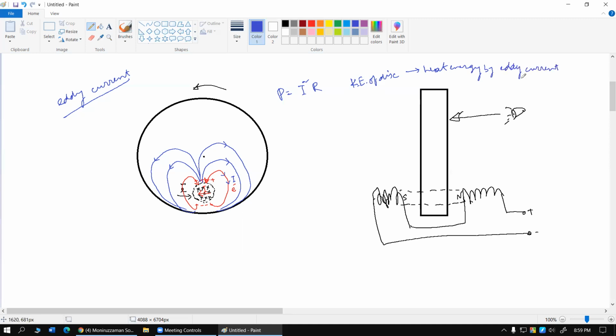which means as long as we keep the magnetic field turned on and the eddy current keeps existing, the disk is going to start to heat up and start to slow down, because more of its kinetic energy will be slowly converting into heat energy, and this will essentially slow down this metal disk. This is one of the ways to effectively apply what we call an electric brake. So, what we call a magnetic brake.